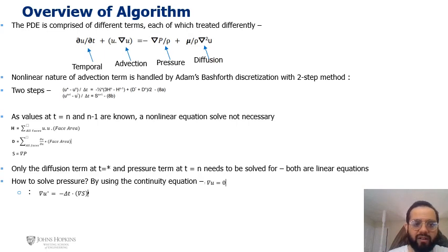So the first part, the u gradient of u, is an advection term. It basically denotes how the fluid velocity is carried due to the velocity itself. The second term, on the right hand side, mu over rho gradient squared of u, is the diffusion term. This kind of denotes how thick a fluid is. If it is more viscous, its diffusion is more, which you can see by this mu factor, which is basically the viscosity of the fluid.